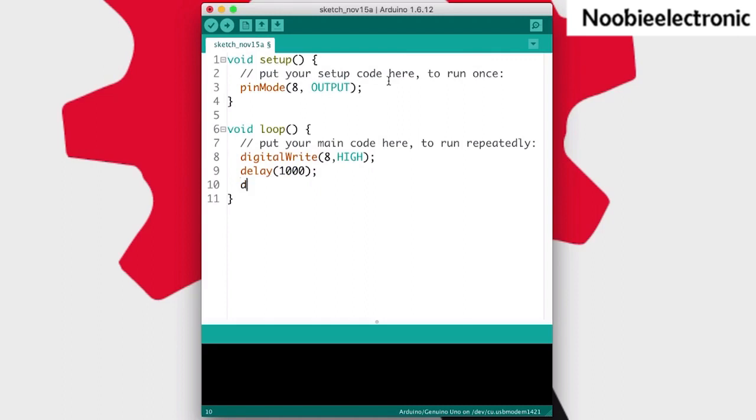And we are only going to change it in the next instruction, line number 10, where again we want to go to pin number 8 and now switch it off. From 5 volts, take it down to LOW, which is 0 volts, the same level as ground. And again, we'd like to keep that for 1 more second.